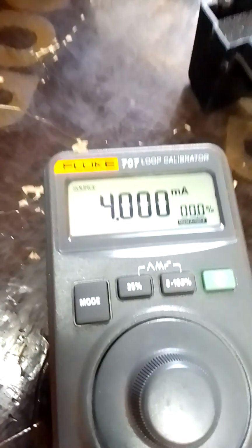As it's changing, it's showing the milliamps, right? The percentage will be showing here. You can use it to simulate your valve, your transmitters. You simulate 4 to 20 milliamps. And if you open your valve, close your valve, it will...